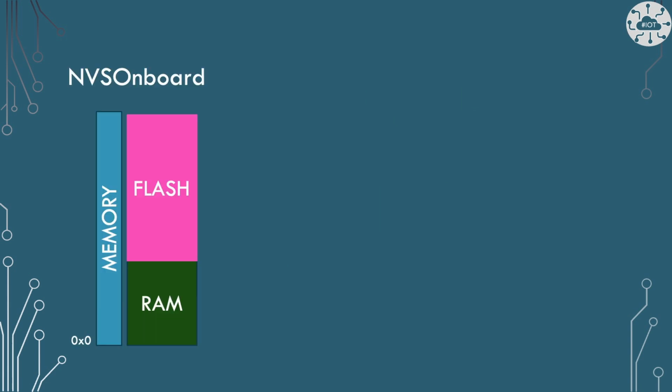And really what I'm doing there is just taking ownership of part of the flash and creating an NVS area within that flash, which is by default, of course, 4K in size. Actually, it could grow and you could have a large one, though generally I think 4K is probably the size that nearly everyone will run and use, because I can't see where you get much bigger than that for this concept.